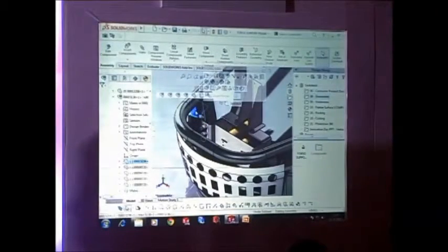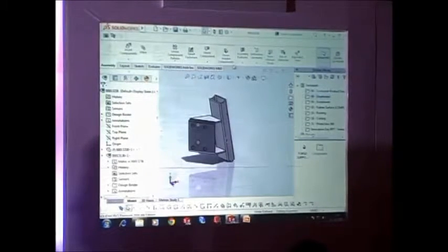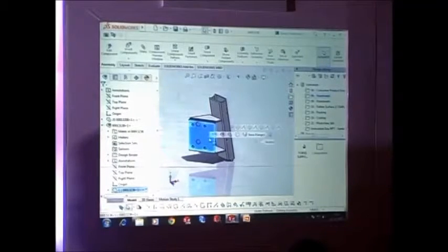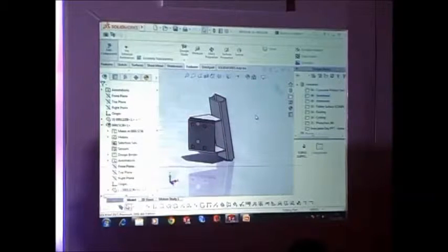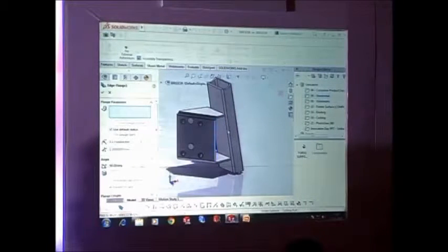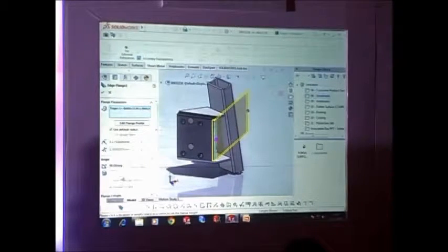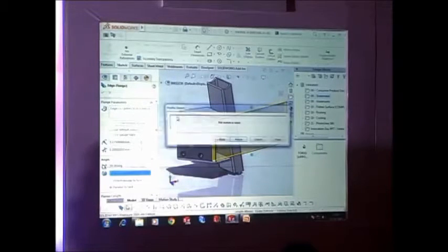Using the breadcrumbs, we can easily select the required model which you want to open and edit. This bracket will not be complete unless we create an edge flange and cut in that to make it attach with the pillar. Creating an edge flange has always been a widely used feature in SolidWorks.